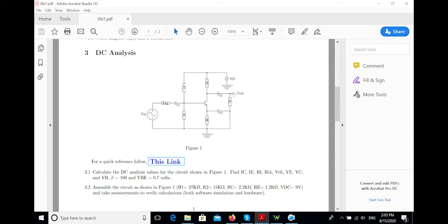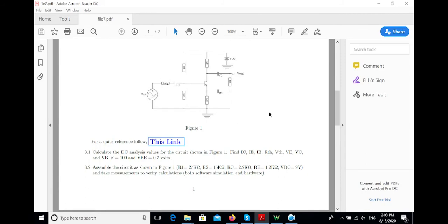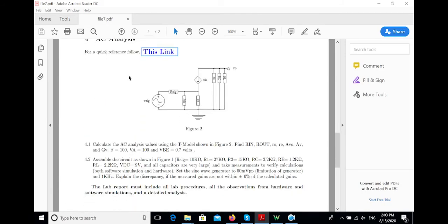So you need to put a probe here and put a probe here. You know how much is the value of the input amplitude, so you don't even need the input measurement. So you just probe here to measure the V out, and then you can find V out to V in as the overall gain of the circuit. So this is not a circuit that you need to build. This is just a help for you to understand the AC equivalent of the circuit.